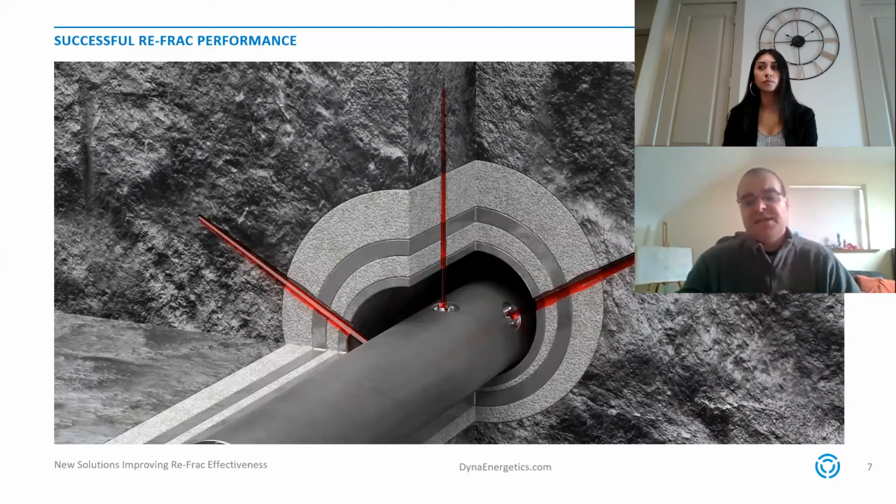These factors are all essential to achieve formation breakdown and pump the design amount of sand and fluids with the available horsepower that we have on surface. Also maintaining the cement isolation, as previously mentioned, between perforation and clusters without secondary fractures in the cement is absolutely critical.